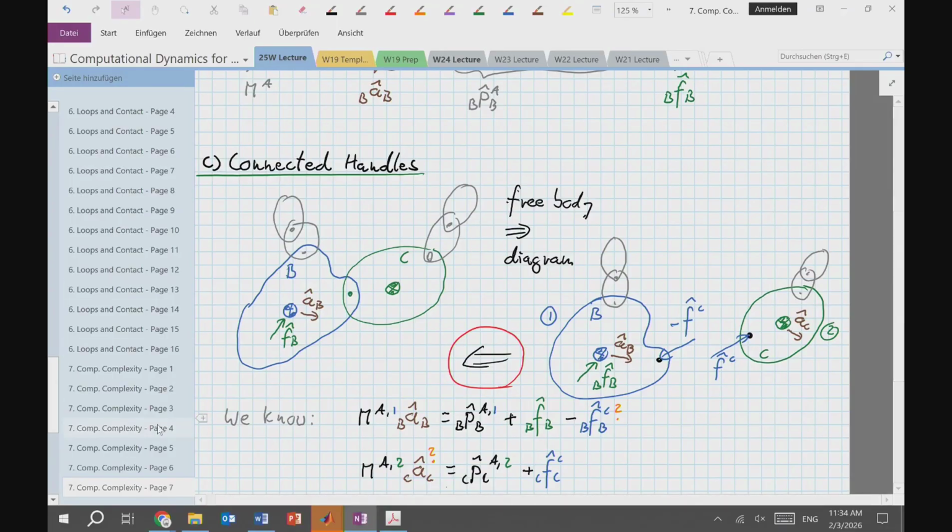The way to understand this, it's easier to think about it the reverse way. If I have an articulated body that I cut apart, which is nothing else than saying I do a free body diagram, all I do is replace that joint here with a 6-dimensional force torque quantity that has some active components and some passive components. But it's basically a 6-dimensional quantity.